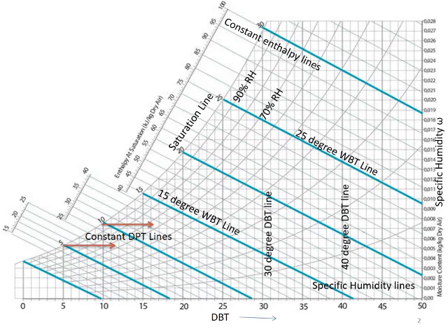For any temperature you want, you have to go from the DBT scale vertically up till it touches the saturation line. Then you have to go horizontally, parallel to the specific humidity lines. So they indicate constant DPT lines. Here I have shown only two lines, 5 degree DPT and 10 degree, and only a small length, but throughout its length, that line represents the constant DPT.